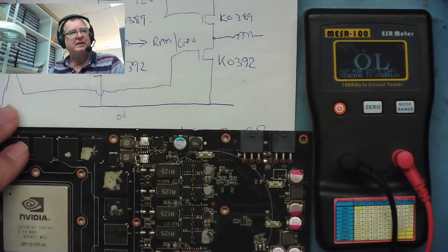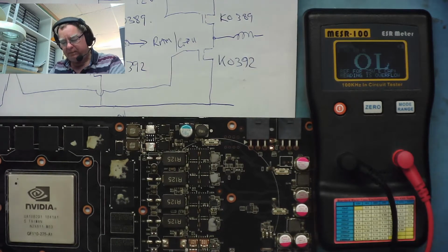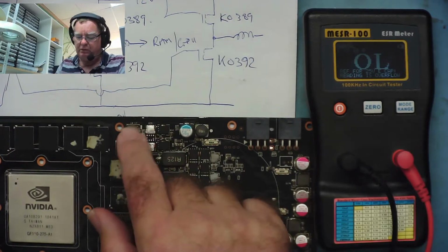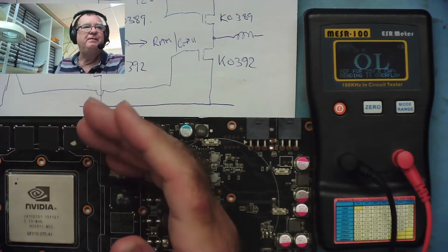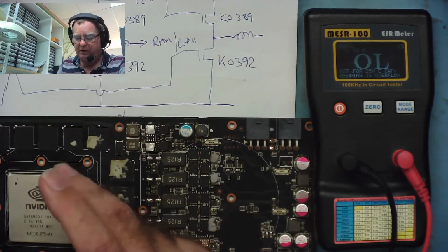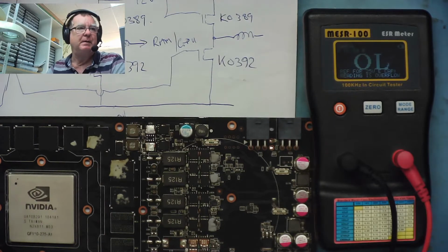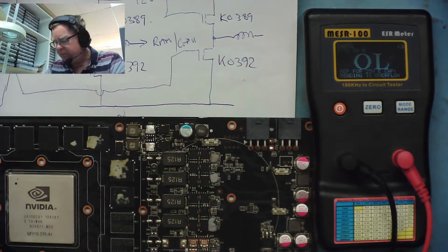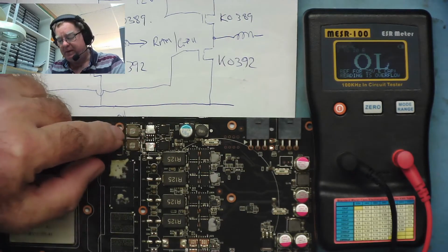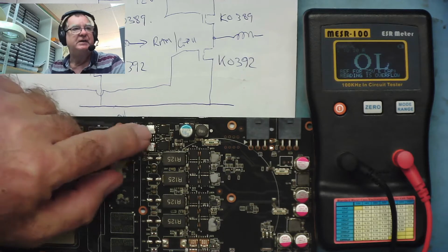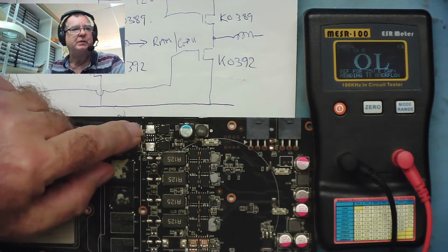And what's happened with this, I'm pretty convinced, is when I started off and I found a low resistance here about 10 ohms, from then on I've been convinced, rightly or wrongly, I've either got a faulty GPU or faulty RAM because it's not easy to fix, and I'm thinking, well, that's just my luck. And I was measuring from either side of this coil 9 ohms on a DC multimeter, and you can't see any difference one side to the other.